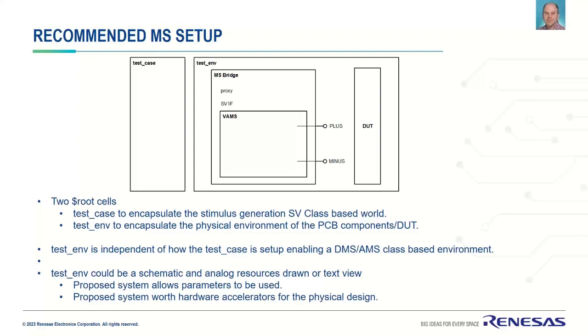But then in the AMS case, wouldn't you have to have an instantiation of the bridge? Yes, as a thing, but most schematic capture tools can handle a package. What I would personally do is make the test bench a SystemVerilog view, because there's no point in drawing a schematic of your test bench. You're going to have so many components there, no one can read them. The ones I see drawn nowadays are like A0, and you can't see what's happening, and nets aren't named.